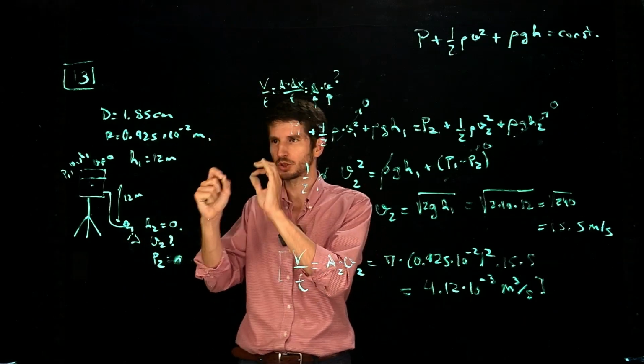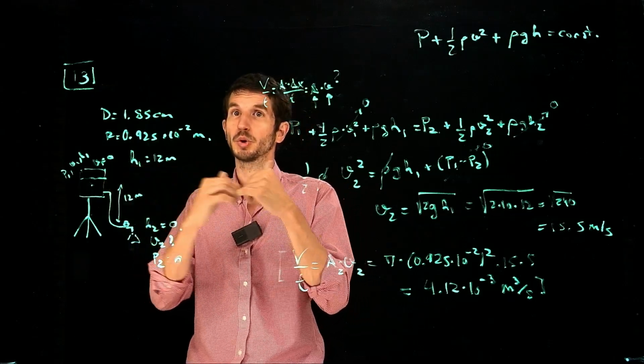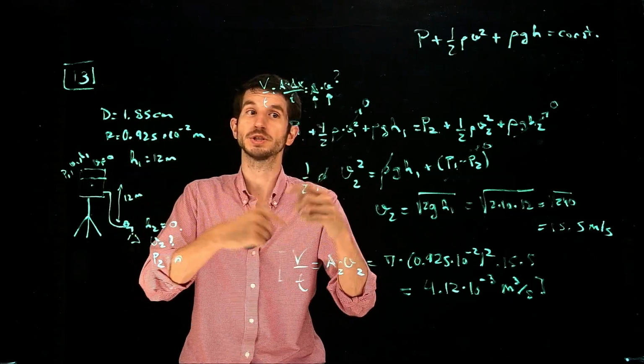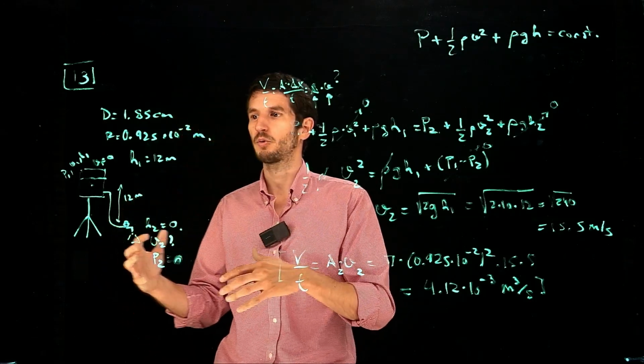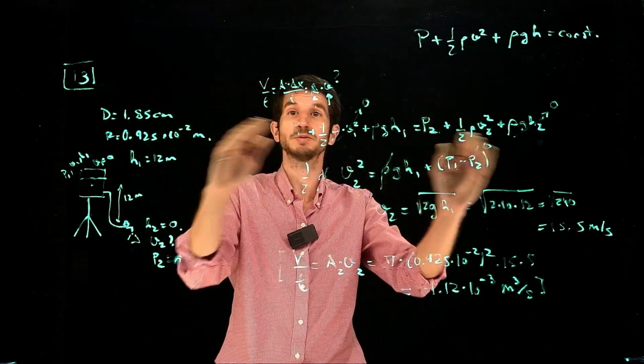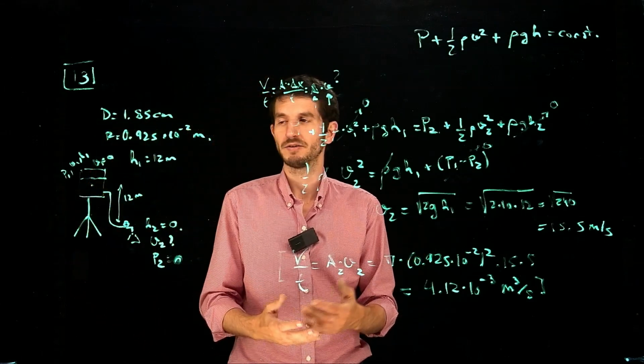So just see the situation and observe everything, what it means. What is the pressure? What thing is acting on the system doing work? In this case, the pressure is doing work, which is why we derive the Bernoulli theorem, right? Because it's conservation of energy with external work. If there was no external work, then it's purely kinetic energy becoming potential. It's like dropping an object. It's the same. But now we're having it with liquids, right?